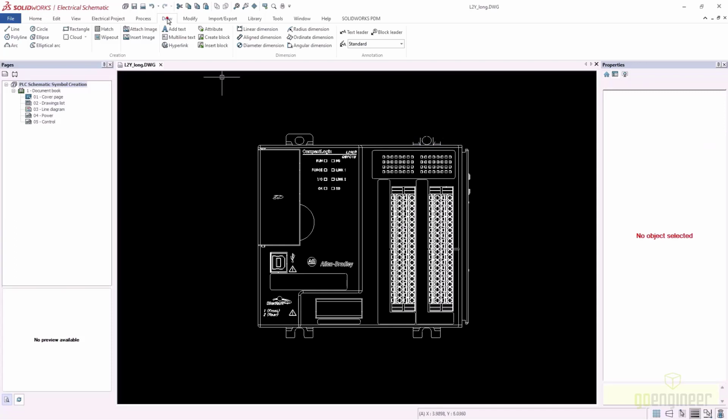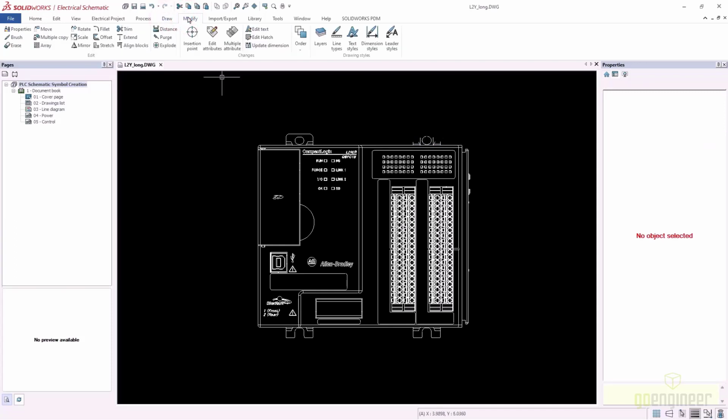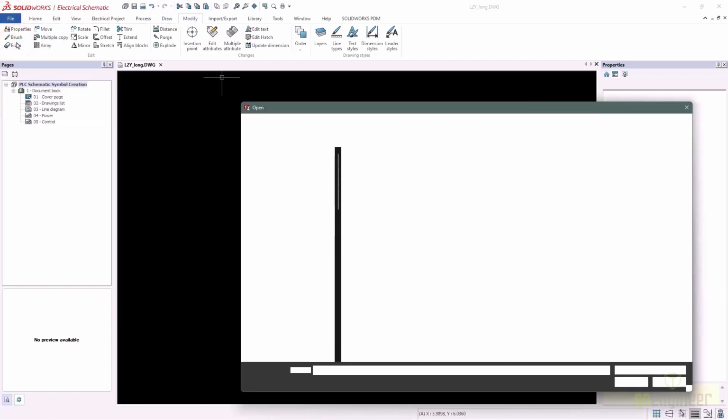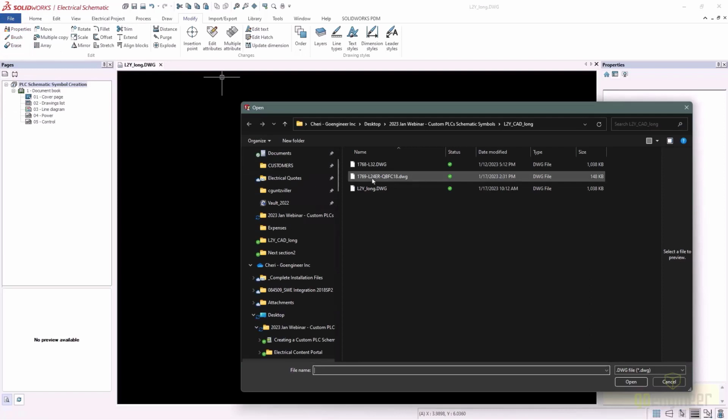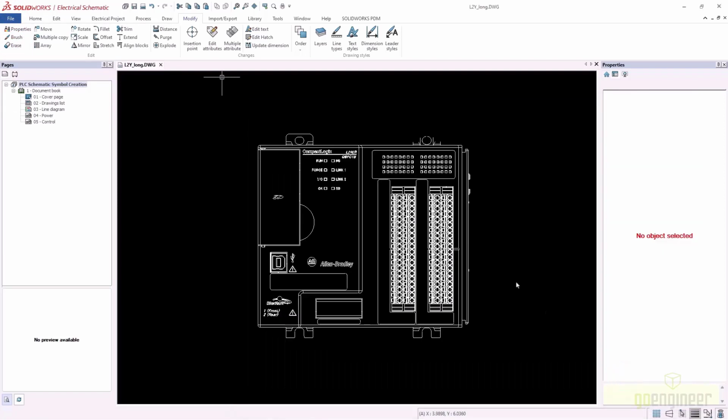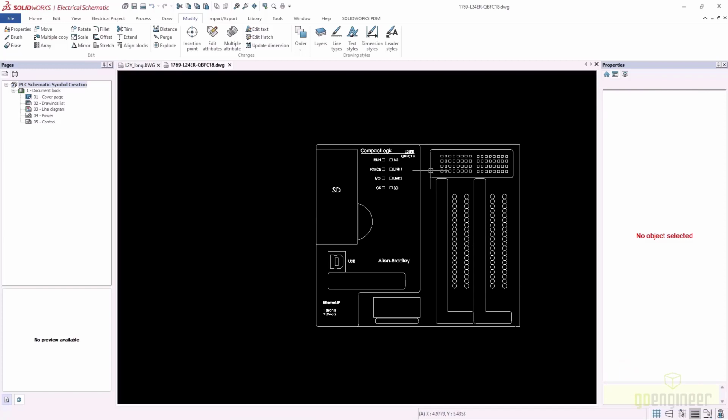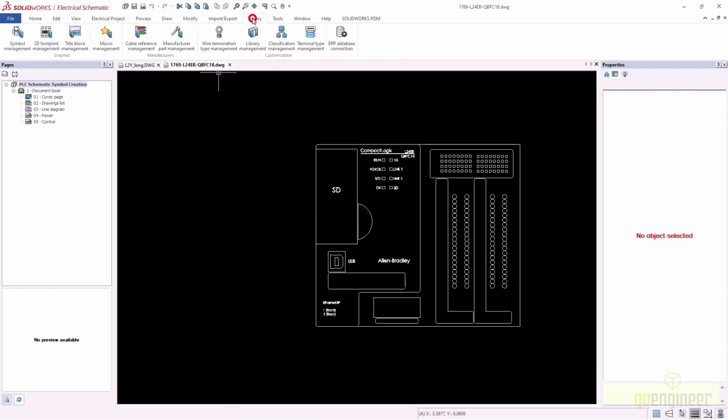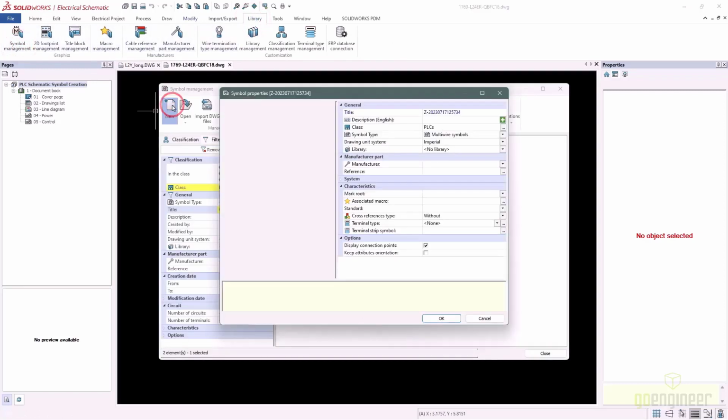So simply using your highlight and delete keys, as well as your draw and modify, you can change text so that you're not using a label. Here's what my drawing now looks like after I complete it. I moved things and put circles in. I put standard text in instead of some of those labels that they had. It makes it a whole lot easier to use.